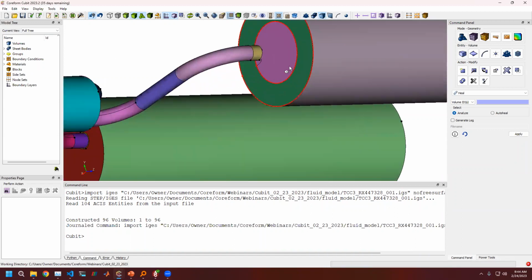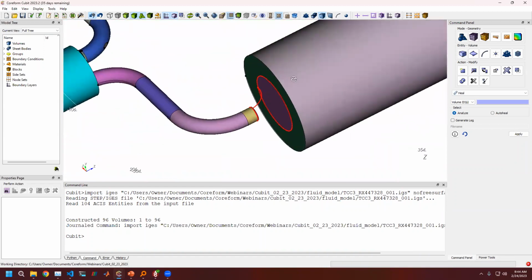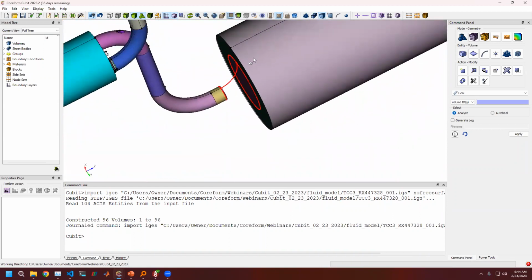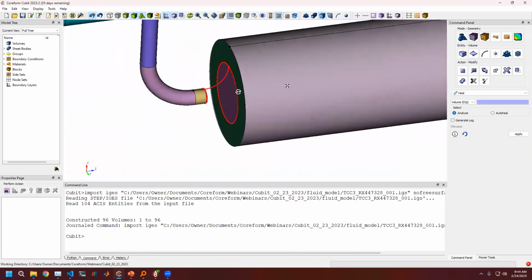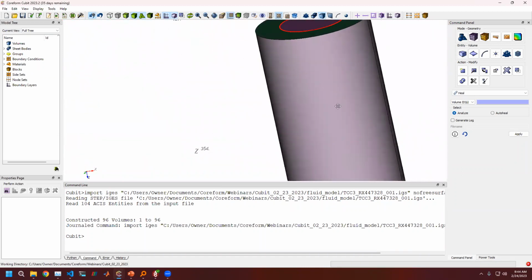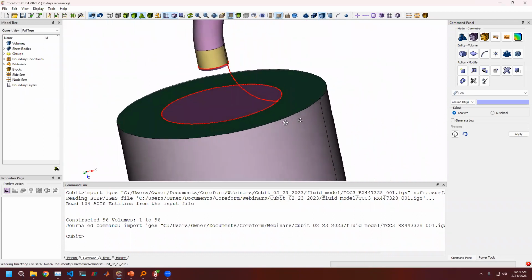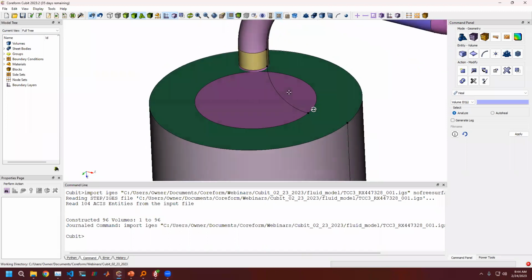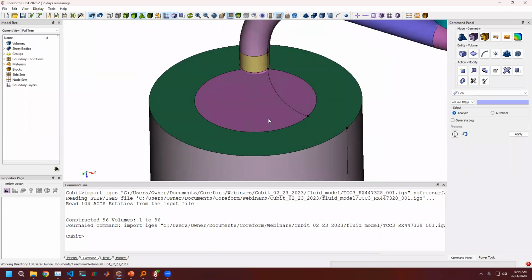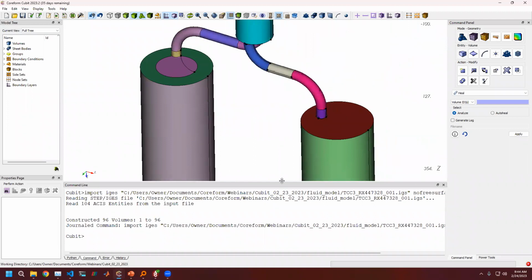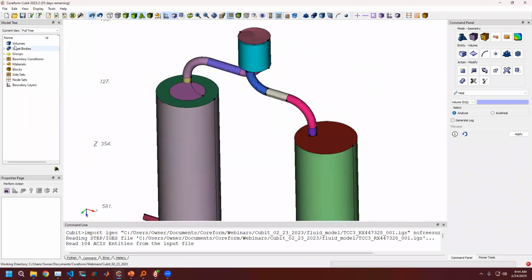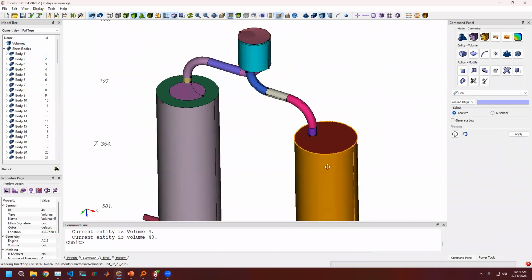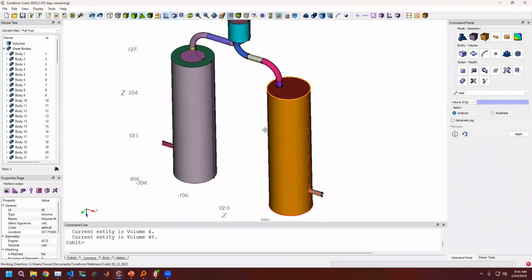And just to show that surface that we saw previously, its representation just wasn't quite able to be captured. It could be an issue in Cubit's ability to render that surface or understand what that surface is, and its translators could. You'll see that with whatever tool you use, it uses certain versions of translation tools that may not be compatible with the version that the original model was built in. What you'll also see with this IGES file is that everything comes in not as a volume, but as sheets. It's really a whole bunch of individual surfaces, and it doesn't define any volume.